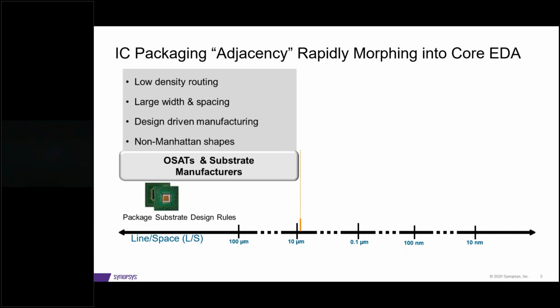Historically, in the packaging world, we've been able to provide a solution for a single die and also, to some extent, multi-die integration in a package using the same organic or different types of packaging substrate. Now, the technologies used for implementing these types of packages tend to be on a lower density routing. The smallest cutting edge spacing and width of the traces are about 8 micron, as far as I have been able to find out. Sorry, not 0.8, but 8 micron width and spacing.